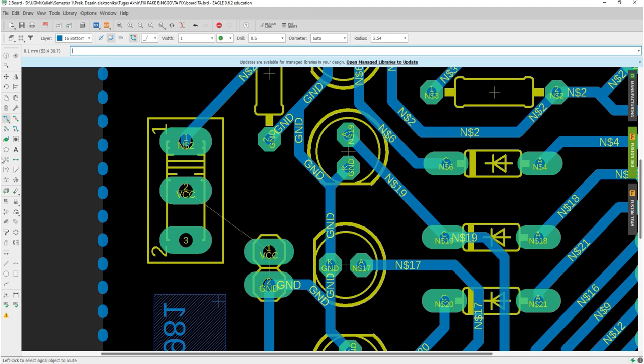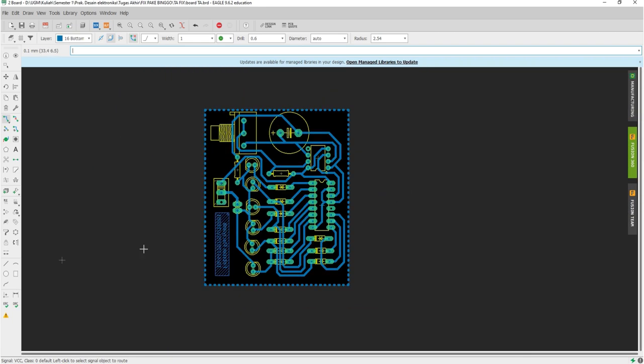Why? Both power and ground traces will have more current flowing through them. And if you don't make them wider than average, you'll have a ton of heat trying to flow through those skinny spaces, which can end up burning wires and ruining your board.